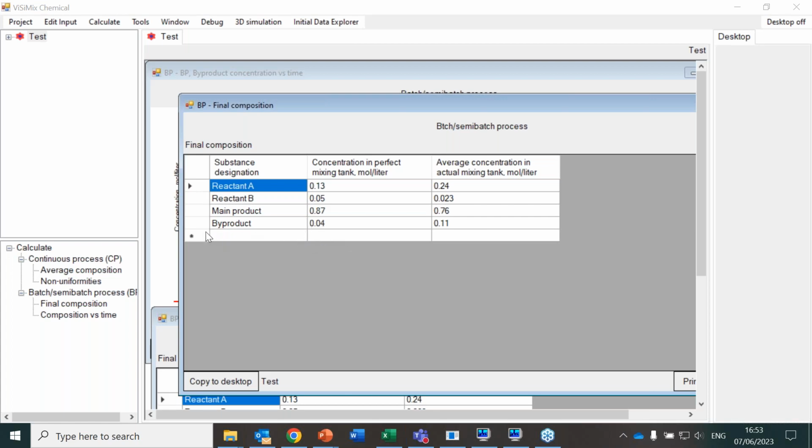Yes, of course. When we are working with 400 liters or 4,000 liters, the mixing parameters that control the reaction are the flow in the tank, so the macro mixing time, and the micro mixing time. When we change the equipment from 400 to 4,000, the energy dissipation around the impeller and in the bulk will be a little different. And the flow, the macro mixing time, can be different.